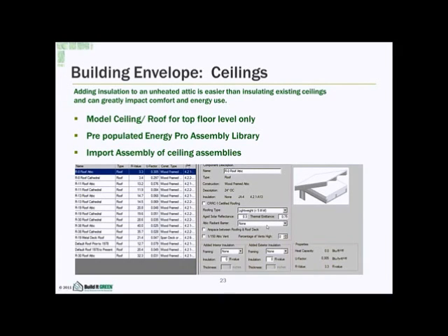If you have a radiant barrier, you're going to have a drop down and select the different types. There's continuous, and there's continuous with skip sheathing, I believe. And if you are modeling this per Title 24, that's because Title 24 asks that when you install a radiant barrier that you also add an airspace and do the 1 in 150 attic vent and have a 30% high roof.